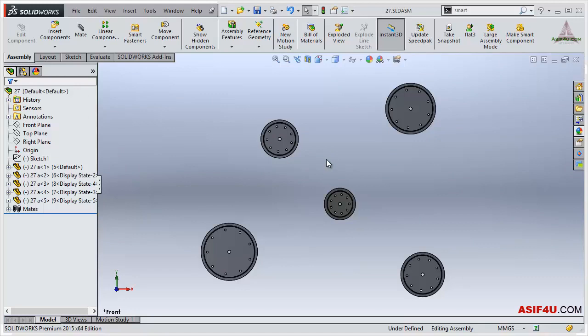Suppose you want to calculate your belt length, and you can see there are a few pulleys here. Suppose you already created one machine, inside the machine you have these 5 pulleys here and you need belt length, you need to calculate this belt length. So in that case you can use this belt chain feature. By using that belt chain feature you can get your belt length, and you can also add your belt as a separate part in your assembly.